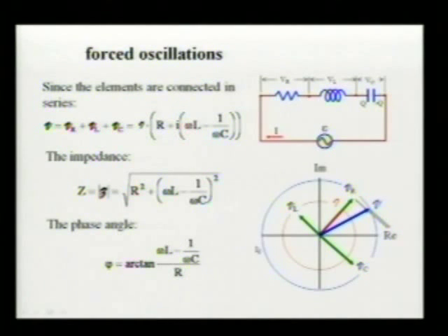It was the difference between those two phasors, and if we pull out I from everything, we will just have the difference in impedance of the inductor and capacitor. And now how long will this one be? It will have Im, the peak value of the current, multiplied by resistance.